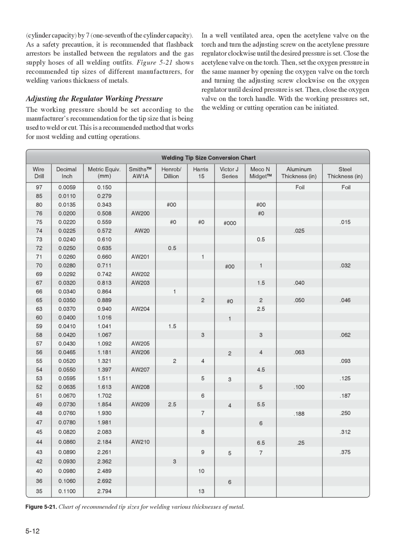Carburizing flame. The carburizing flame burns at approximately 5,700 degrees Fahrenheit at the tip of the inner core. It is also referred to as a reducing flame because it tends to reduce the amount of oxygen in the iron oxides. The flame burns with a coarse rushing sound, and has a bluish-white inner cone, a white center cone, and a light blue outer cone. The flame is produced by burning more acetylene than oxygen, and can be recognized by the greenish feathery tip at the end of the cone.